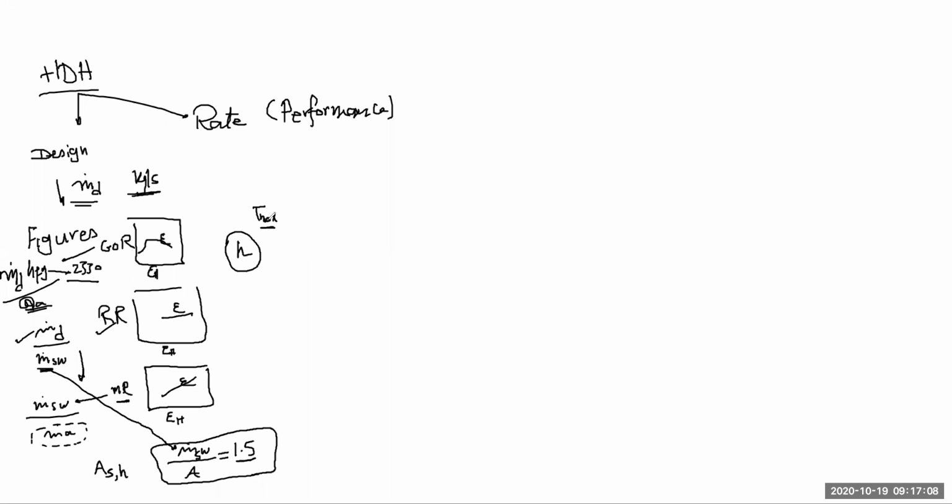So we're talking about some sort of standard steps that you are going to follow in order to do a thermal design of the unit. I can expect that when I'm asking you to come up with a design for an HDH system, I would have results that are not similar, because there's a human factor when you get a value from the figure. Somebody can calculate the GOR as 1.9, another one as 1.95, 2 or 1.8. Something like that is acceptable as a tolerance in the solution.